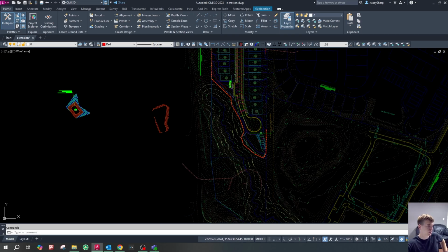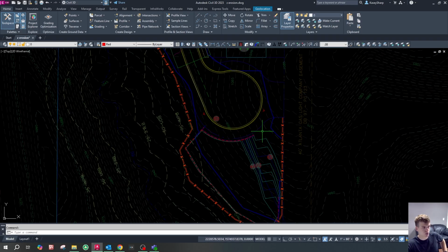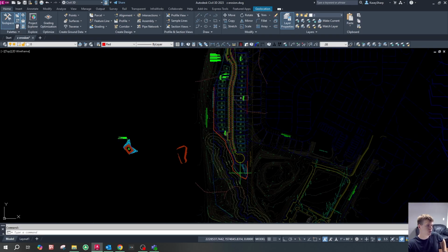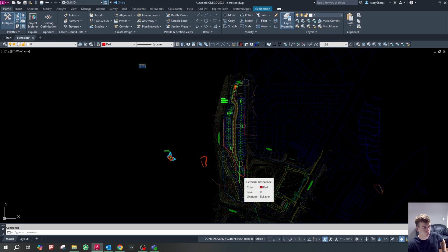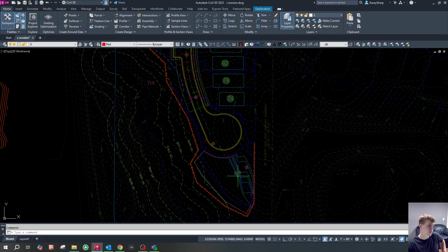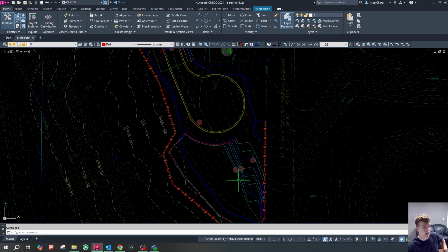What we're going to do is use a very common strategy that we use all the time when we're doing our erosion and sediment control plans, which is using the ponds that are eventually going to get graded in phase 2 as our sediment traps in phase 1. Effectively, the contractor can go out during phase 1 and grade out a portion or even the entirety of their ponds, right? That big hole that they dig out, because that's all it is, doubles as the sediment trap or basin.